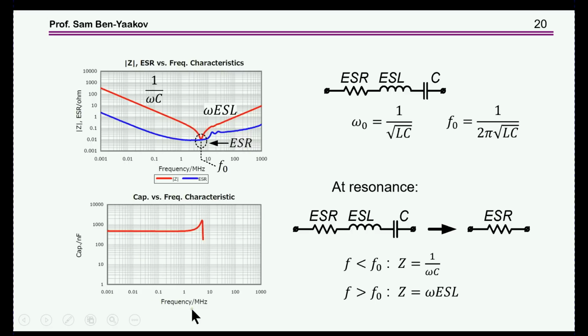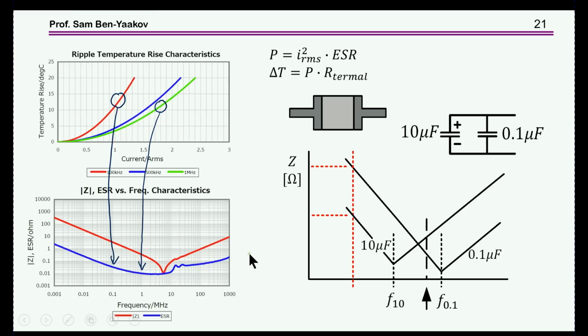Now, the capacitance change with frequency is usually not that much. Up to here it's not capacitance, it's a complex impedance because they hit the resonance, but you see it's pretty constant. Another information the vendors are giving is the current that is allowed.